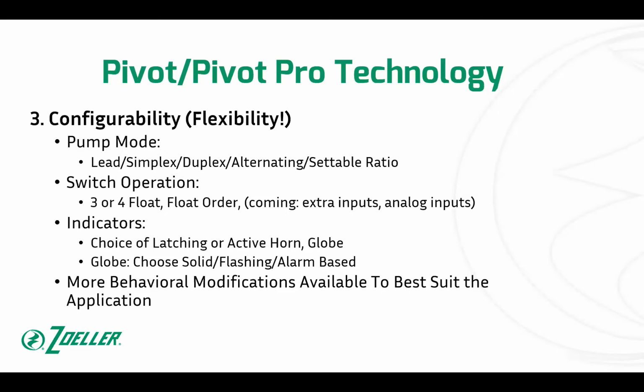That makes it real nice. The homeowner can be at the kitchen sink and see the panel is in alarm, and on the phone describe the blink sequence to the contractor. And the contractor can look that up on his cheat sheet and see that that's a bad contactor or whatever it is, and know what he's getting into, and maybe even make a recommendation to the homeowner over the phone. Who knows? So that has already proven itself pretty handy, even for a panel that's not connected to the cloud.